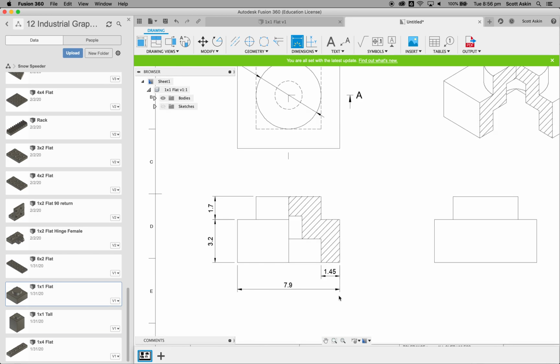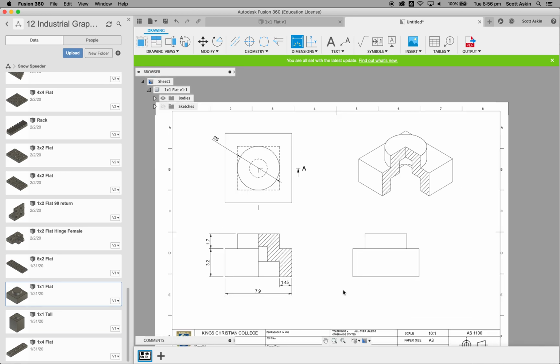And that looks pretty good to me. The other thing we need to do now is to put in some center lines. So center lines, when you're looking down on top of a cylindrical object, we use this icon up here, the center mark. You see then as I come over this circular object, I click once and it automatically puts the center lines in like so.